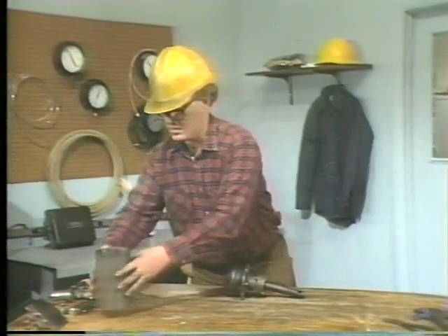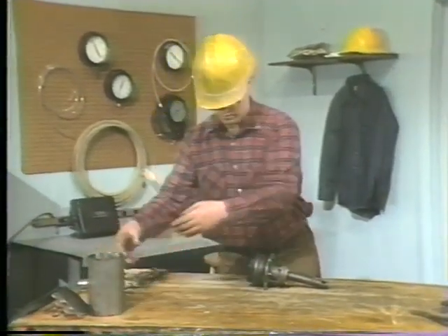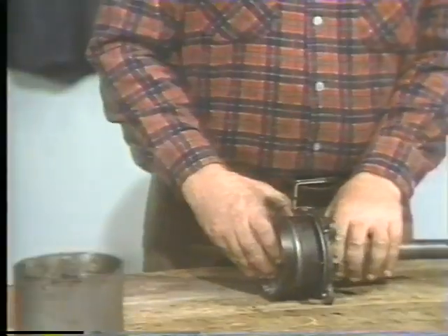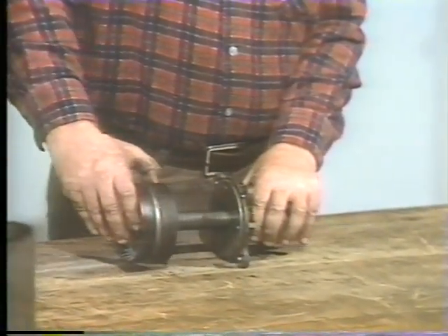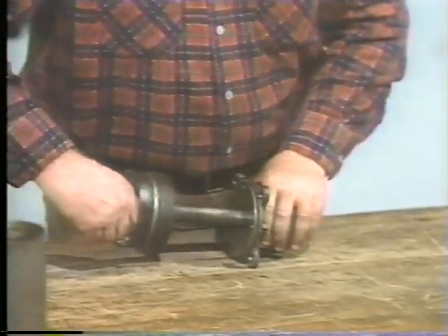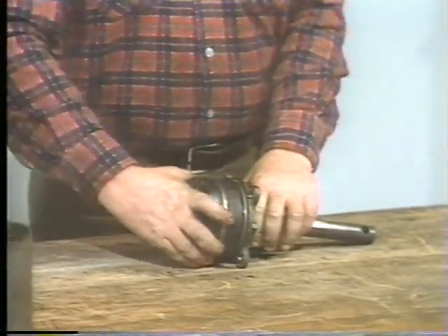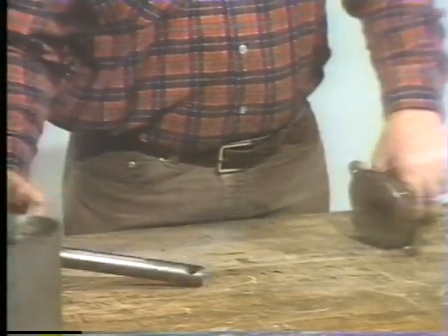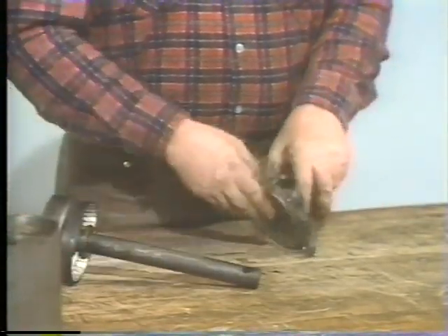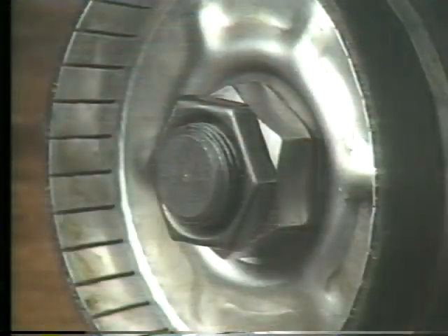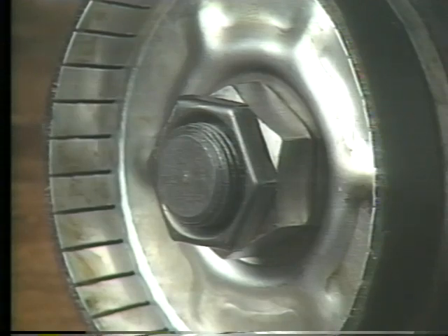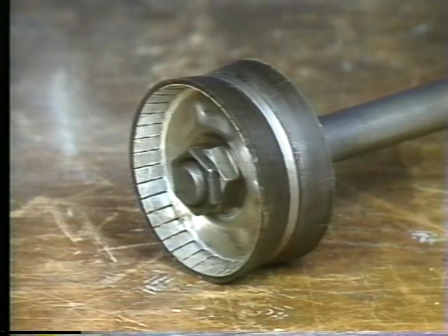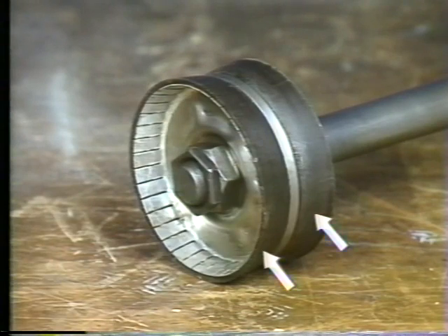Now that the cylinder has been removed, the technician can separate the individual parts of the piston assembly. The piston is a cylindrical-shaped device that fits inside the cylinder bore. Changes in air pressure cause the piston to move, as we will see when we describe how this actuator operates. The piston assembly is mounted on the end of the piston rod and held together by these nuts. This piston has 2 cup subassemblies, which create an airtight seal between the piston and the walls of the cylinder.